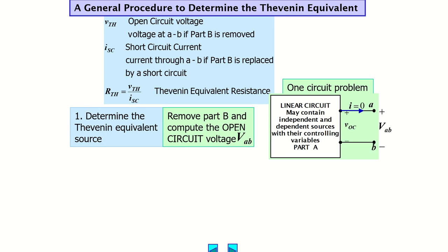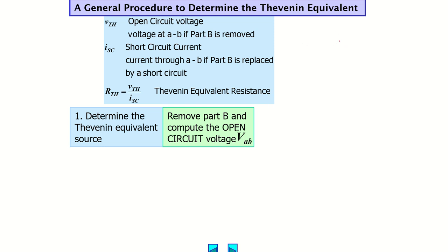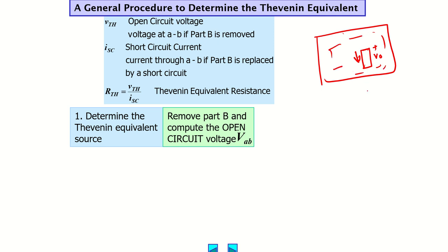So the backbone of Thevenin is based on the fact that if you have a very complex circuit, and let's say there is a branch here and you want to find out what is the voltage drop across that branch, or for example, what is the current going through that branch, or power whatsoever. And we have the rest of this, which is a quite complex circuit. What we will do is take that load branch out of our circuit. Okay, so this is our load, and then we will create an open circuit at that point.